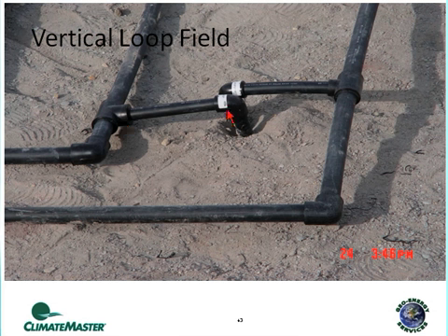The problem with that, though, is the contractor has got to relieve the edge here of that borehole, because if he risks bending that pipe over, he might kink the pipe as he bends it over if he doesn't put relief on that lip there. So it just comes down to contractor preference or even designer preference.